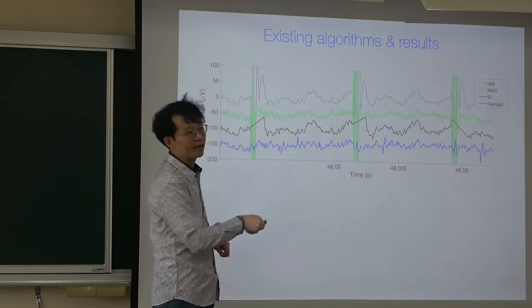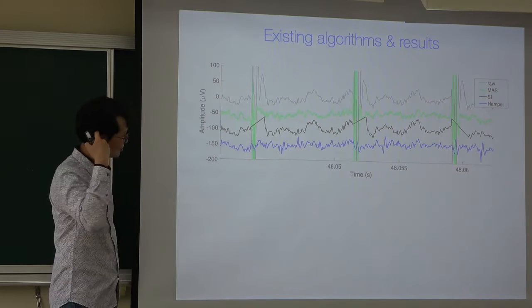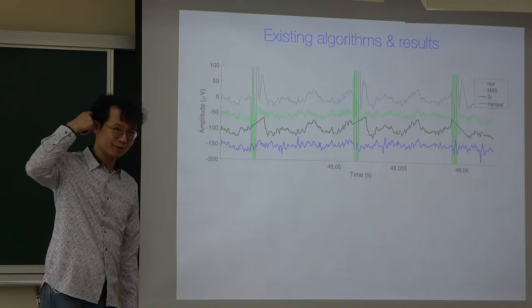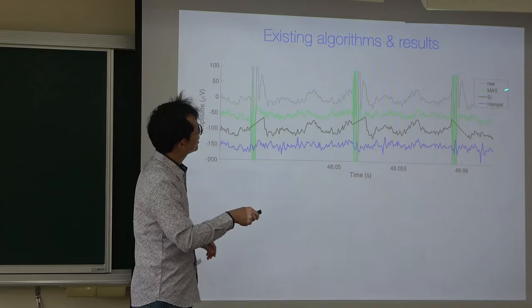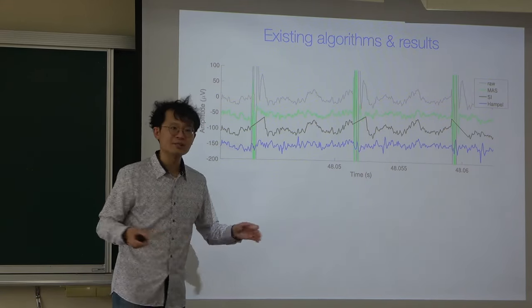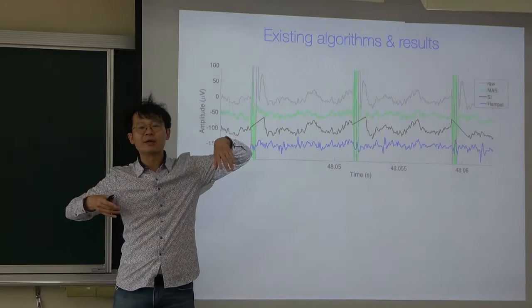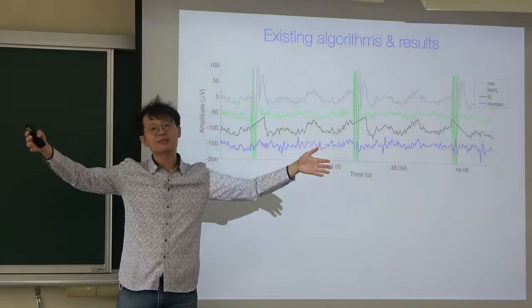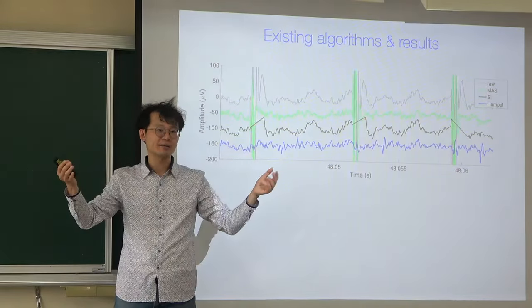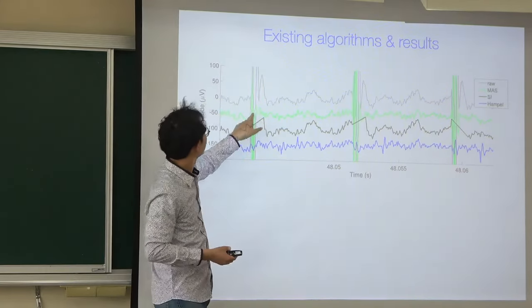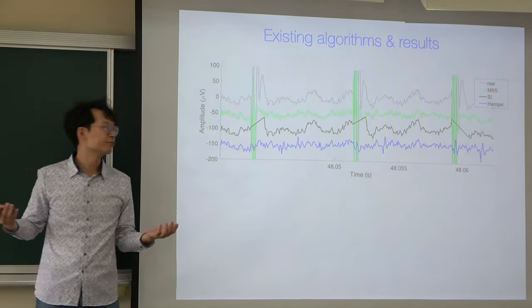For example, this is moving average subtraction, this is SI, subtraction and interpolation, I remember, and this is the Hampel filter. What you do in MAS is very simple. Because the stimulation is so similar, spike after spike, we take maybe 10 consecutive spikes, evaluate the average, view it as a pattern, and subtract it from each stimulation artifact. And maybe we can recover the local field potential.